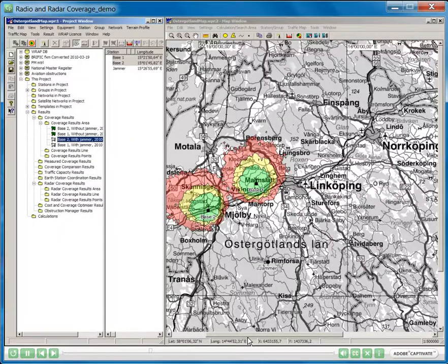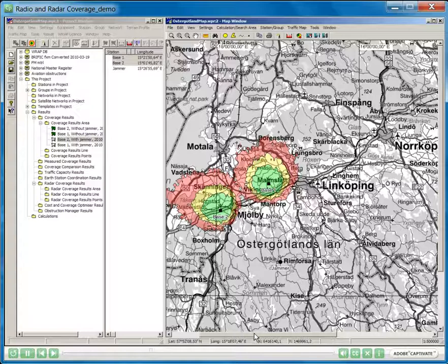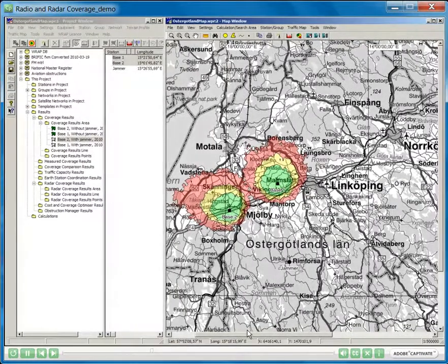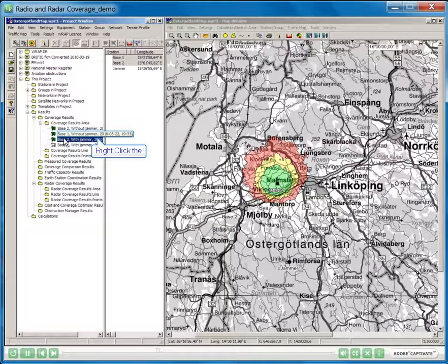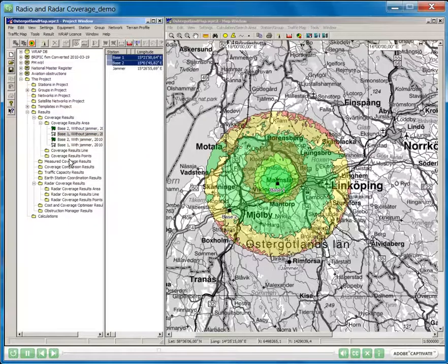And it is typical that we have this unsymmetrical appearance of the ridge since we are calculating receiving in the mobile, in the 2-meter high mobile antenna. And when it is far away from the jammer, it will have less signal from the jammer and comparatively more signal from the base. And when it comes to the jammer, it is the reverse. So showing both at the same time, it is quite evident that the range reduction is severe through this jammer.